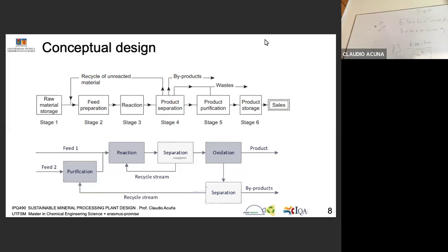Recirculation is always good, because you either play with residence time, you have a degree of freedom of a reactor, residence time. And we already talked about what happened in grinding. I hope you study a little bit more on grinding, why we have recirculation. You remember we talked about that? The recirculating load. In the primary grinding, you use a circulating load of 300%, 400% in order to have a tighter, closer particle size distribution. Why do we want to have a more narrow distribution?